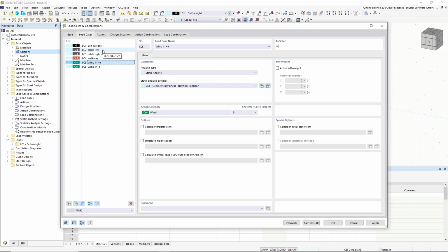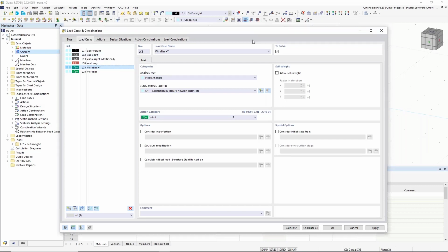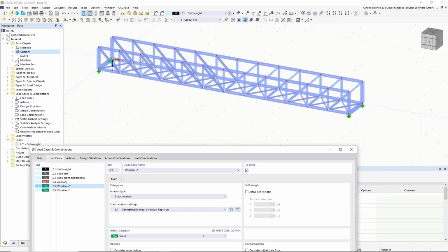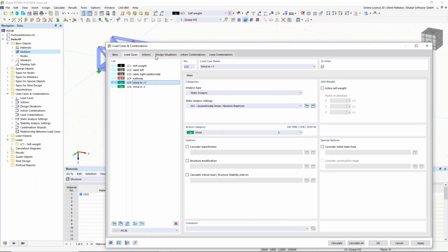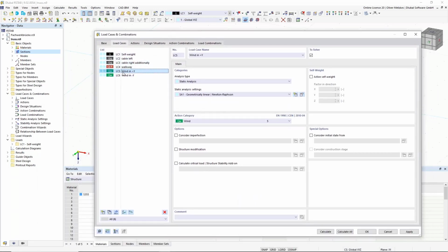So I don't have, for example, temperature loads, to simplify it a bit. Also, in my structure, as I have modeled the supports this way, a temperature load would just increase the length, but there would be no internal force from that if I have this uniform temperature load, for example. So I would say for now, that is okay to have this simple structure of load cases.